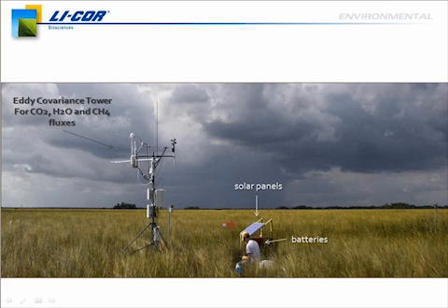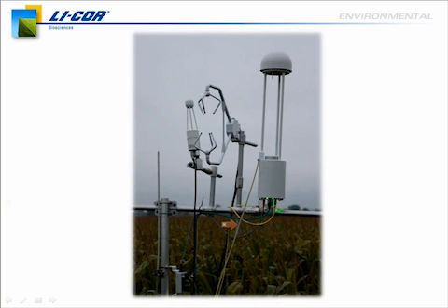Now, here's an image of an instrument deployed over a cornfield, in conjunction with an LI-7500A. I just want to use this to point out some of the key points about the LI-7700. As I mentioned earlier, there are heated mirrors. Both the top mirror and the lower mirror are heated, but they're not adding energy to the system much. They're just keeping the temperature of the mirror slightly above ambient, so those mirrors don't become places for water to condense. This lower mirror is actually spinnable, and we do that so that we can clean the optics, and I'll get to that in just a moment.